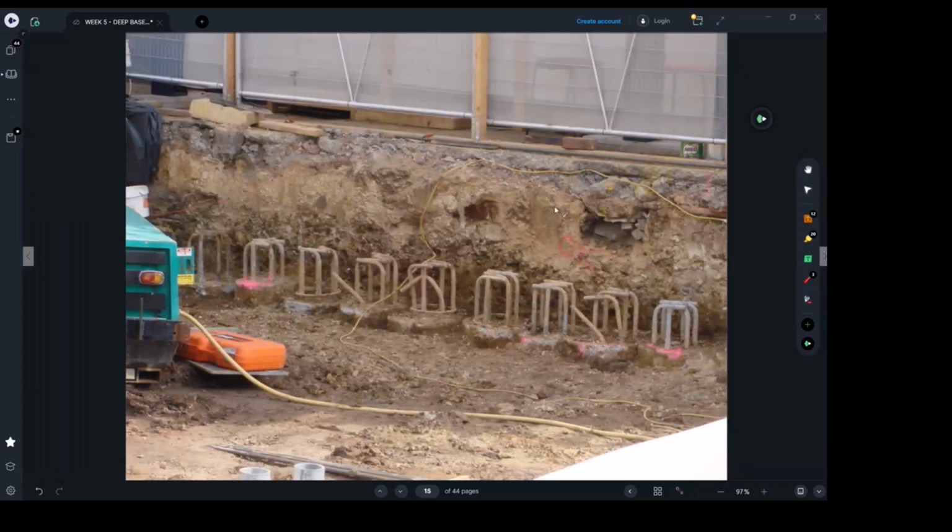Here are some pictures showing you those contiguous piling systems. They are very closely spaced, and it seems that the soil here is a sand material which cannot withstand more than about a 100 millimeter gap, which is specified by the soil report or the geotechnical engineers.